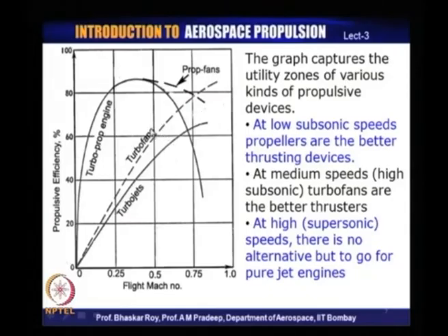And as a result of which, these turbofans become more and more competitive at a high subsonic mass flow, these turbofans are clearly the more efficient and more desirable propulsive devices, and that is the reason why most of the aircraft today fly with turbofan engines.